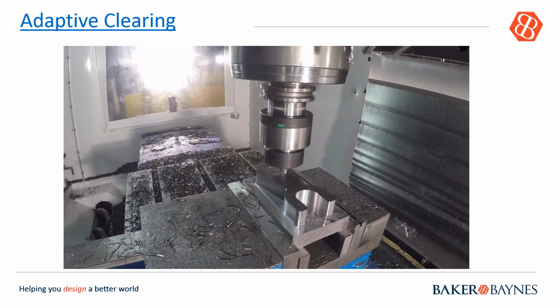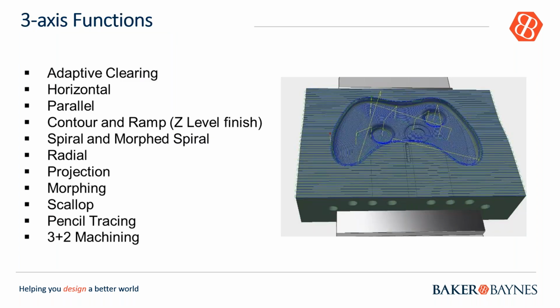If we look at some of the turning operations, again, as you can see in the image itself, you can see this profiling, grooving, single grooving, some facing. You can do parting as mentioned, chamfering, and also the stock transfer, including the mill turn, which is really great, which allows you to do actually both.